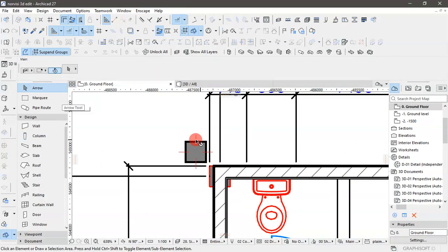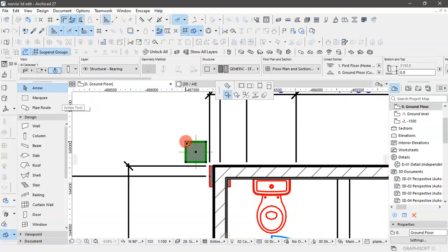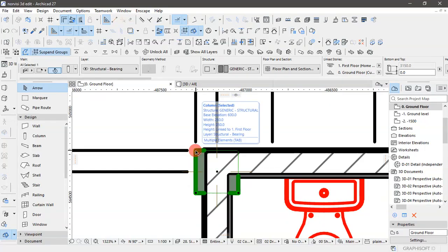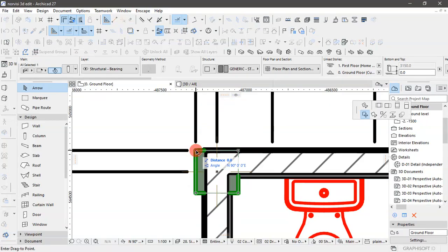Now I'm going to use this to move this side. Then I move to this side. Now I click here. Then I want to create multiple copies. So I hold Control and then Alt. You see now the plus is 2.